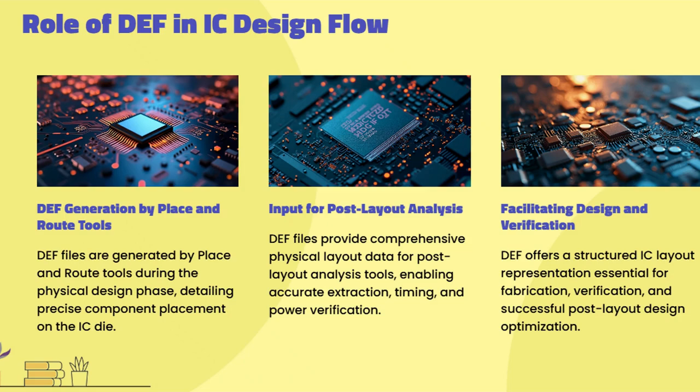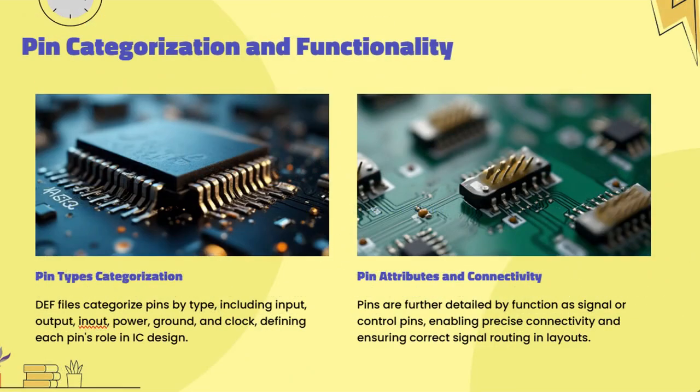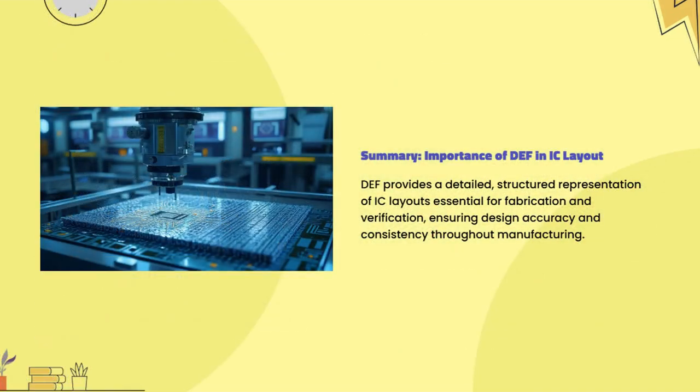It's clear that DEF provides a comprehensive and structured way to communicate layout details. To wrap up, how has DEF influenced the evolution of chip design collaboration? DEF has standardized layout communication across EDA tools and teams, making collaborations between global design centers frictionless. For instance, a team in California can generate a DEF file for a block and have engineers in Taiwan integrate it seamlessly, accelerating development cycles.